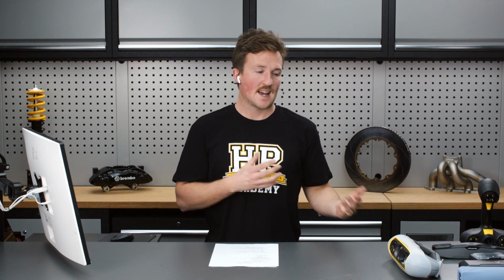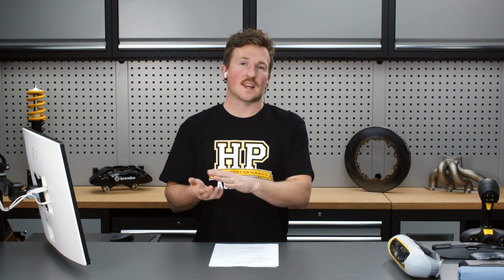On that point, there are also hybrid laser and structured light scanners, like the Einscan HX range. That's combining the strong points of a laser scanner, which is really good at capturing what we'd call troublesome surfaces: shiny surfaces, where the issue is that it reflects too much of the light that lands on the surface, dark surfaces where it absorbs too much of the light, or translucent surfaces where the light just passes straight through it.